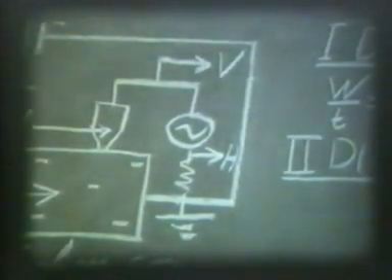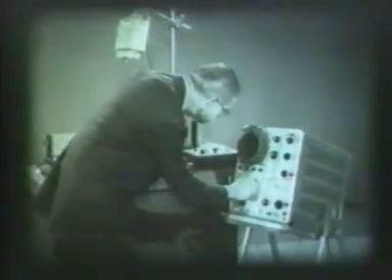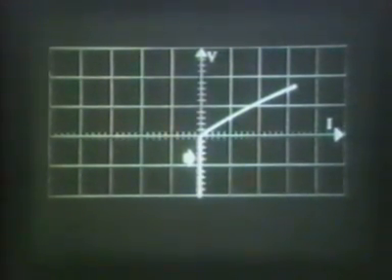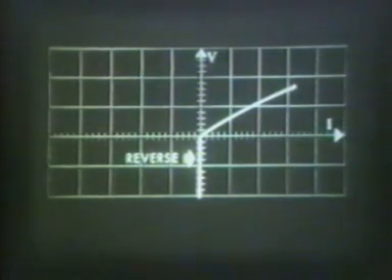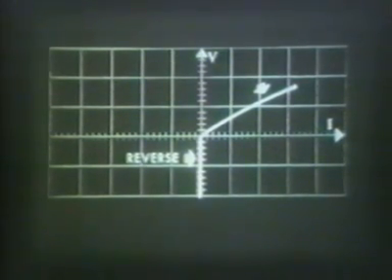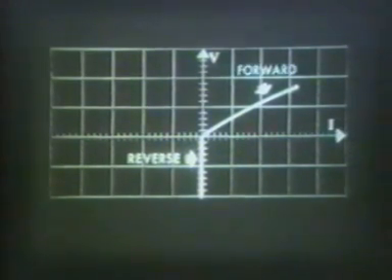The voltage current characteristic on the scope shows that for negative voltages, the current is barely perceptible. This negative polarity, corresponding to difficult current flow, is called the reverse direction or reverse polarity. Positive voltage on the point produces relatively large currents and is called the easy flow or forward direction.